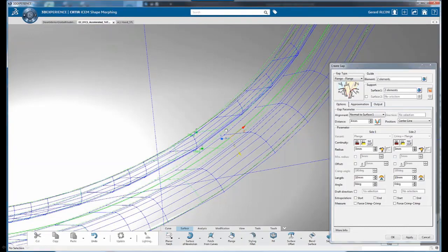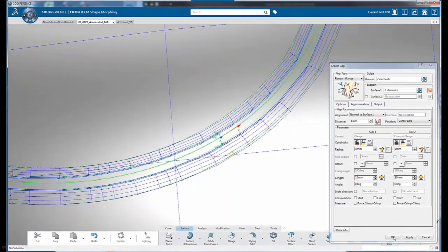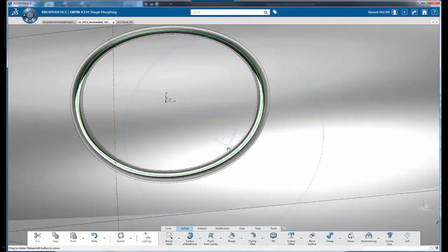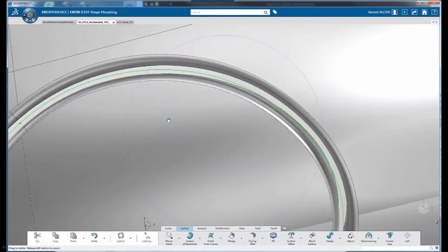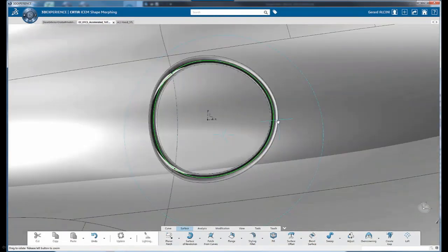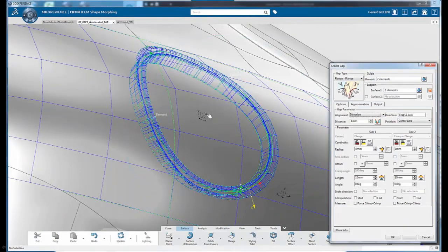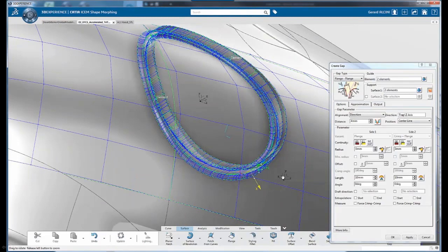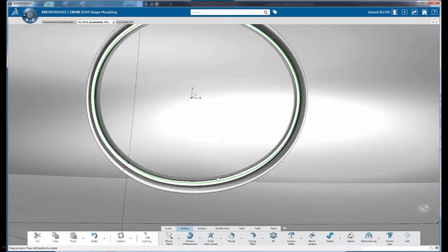And we can input the gap, the continuity of the fillets, and very important, the direction of that flange, which in this case we had normal to surface. Now we're going to pick the direction. We're going to pick the z-axis of that axis system. We can easily flip the surface by just clicking on one of those arrows.